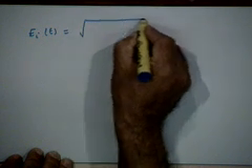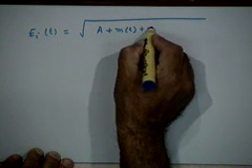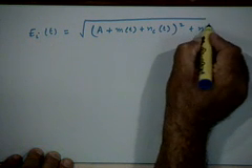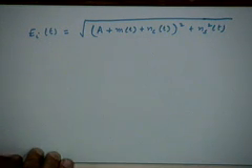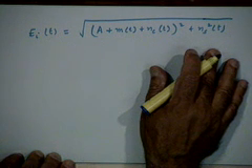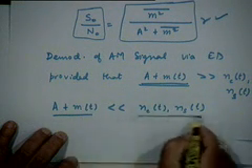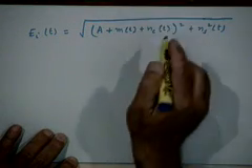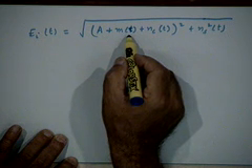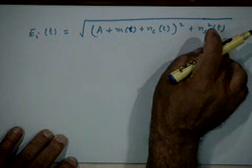The exact expression for the envelope was the square root of the in-phase component, which is (A plus m(t) plus n_c(t)) whole square, plus n_s square t, right. This is the exact precise expression for the envelope with no approximation. When you make this assumption of A plus m(t) being much less than this, basically what it means is that when I expand this term here, the square of A plus m(t) can be ignored, because that is going to be much smaller than either n_c or n_s, right.